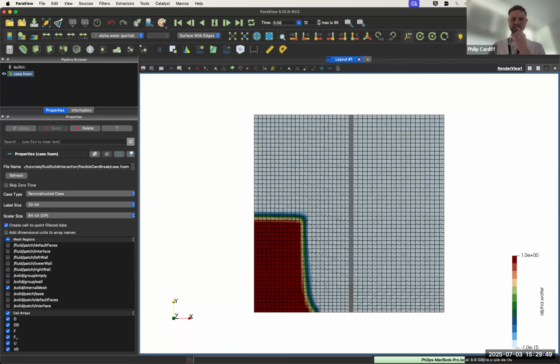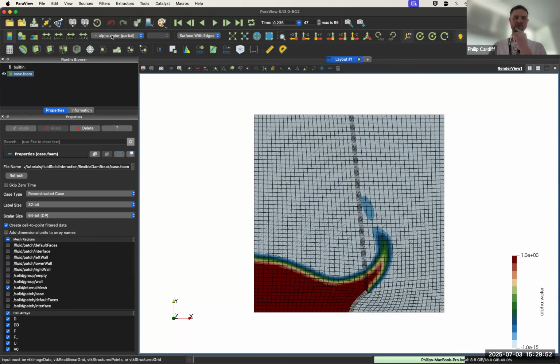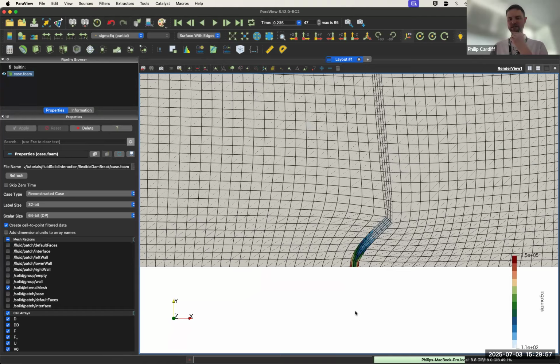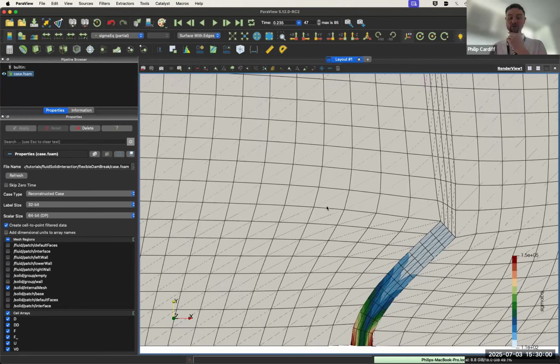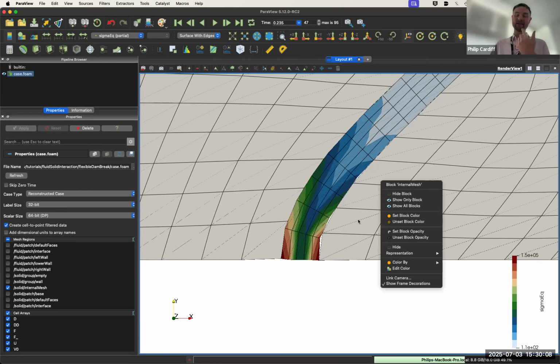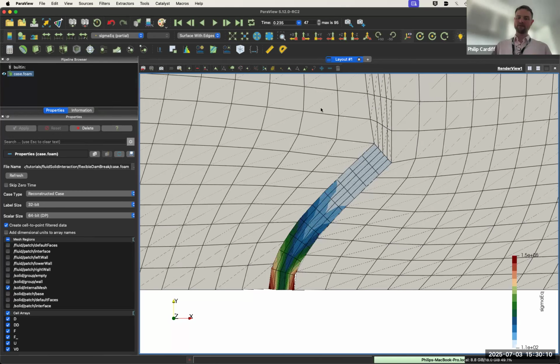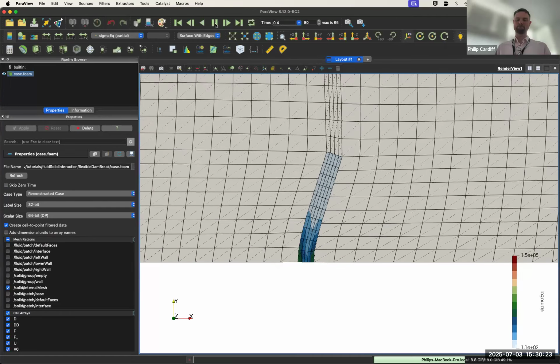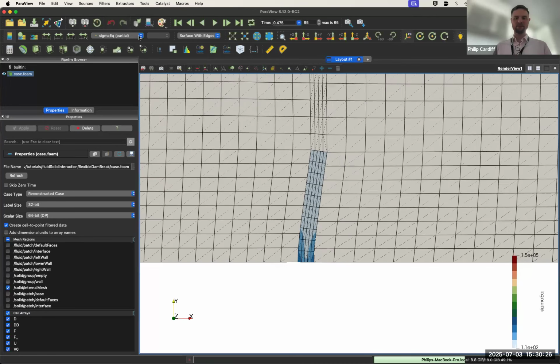So then you get something like this, and you can look at your solid and at the stresses in the solid as well. So it's bending again. It's a very coarse mesh, but you see bending on the outside and the other side. But when you don't have a conformal mesh, you're always going to have little gaps like this as well. That's just the nature of the way you do it. If that's too big, it could cause a problem for the mapping. But in this case, we're calculating interpolation weights in the very first time step. So as long as they're okay, it should be okay afterwards because they're stuck. It's a no slip condition. So this, very good.